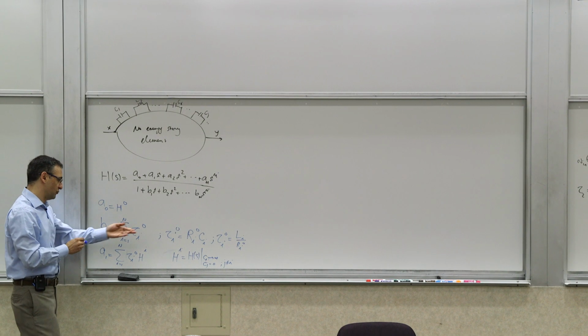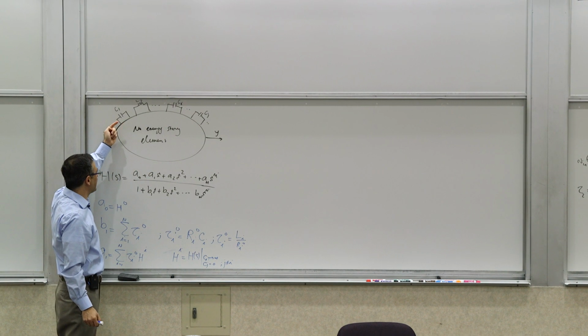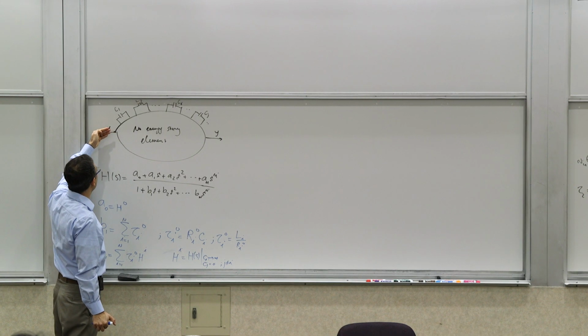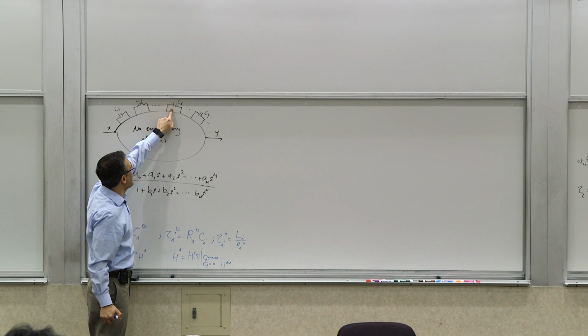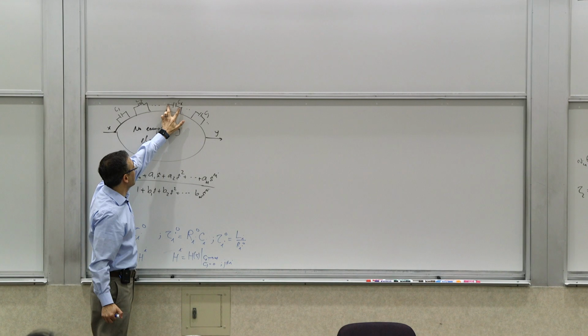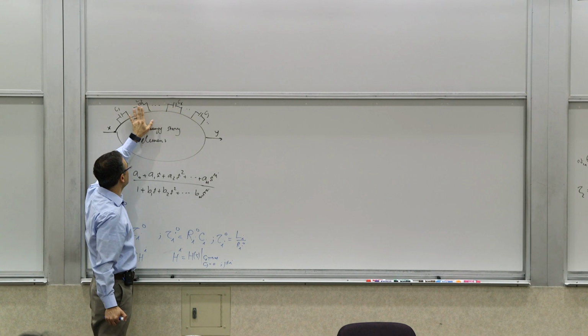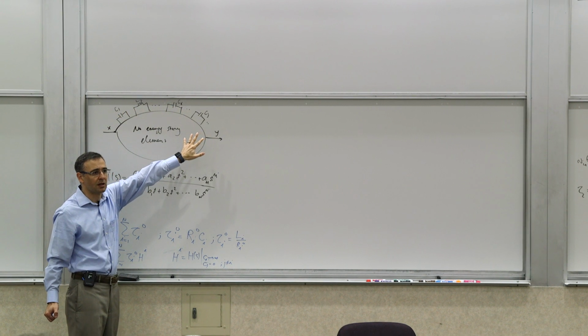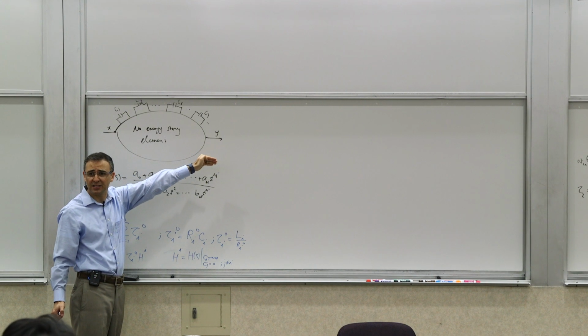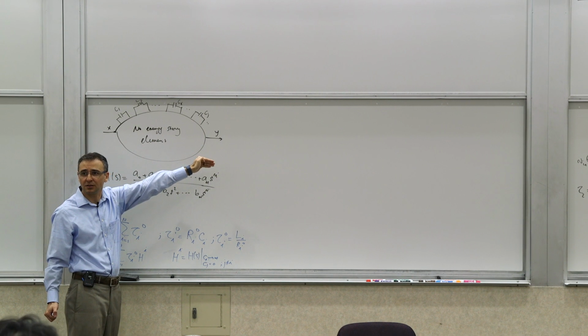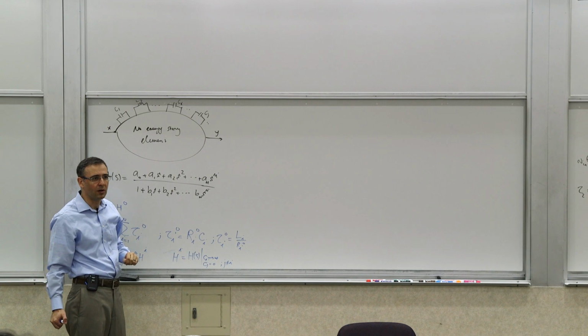Or Lj's, whatever. So what happens is that basically to determine hi, what you did, you said, okay, let's say this element, Ci, I make this infinite value. So in this case, it's a capacitor, it becomes short circuit, but everything else is zero valued. And you look at this, it still is a DC transfer function, transfer constant, right? So these are the things we already knew.